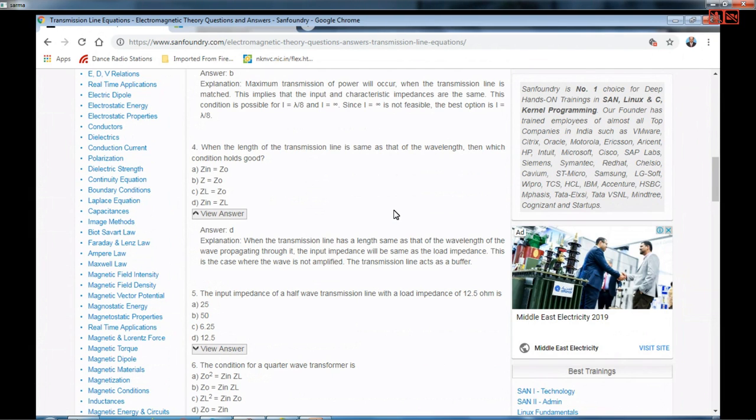The same situation as you find when you go into somebody's house where a dog is kept for security purposes. If you move, then only the dog is going to bark or do something. If you stand still, the dog is not going to do anything, because the dog's eyes are also moving target indicators. So in a moving target indicator, when there is movement, then only must there be an indication. That means previous signal from the target and present signal from the target, we try to compare and see whether there is any difference.